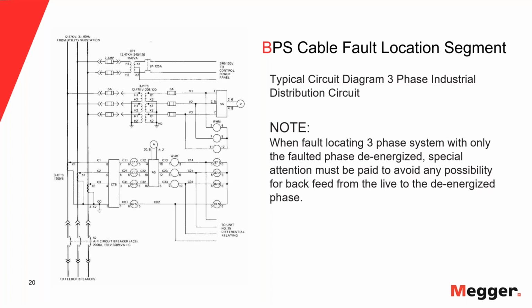Okay, so whenever we do fault locating in three-phase systems, we have to pay really close attention to make sure that when we fault locate on one of the phases, the other two phases, if they are energized, don't backfeed unknowingly somewhere into the phase that we want to fault locate. So there has to be some checking done to make sure that if there are any backfeed points, they are open.